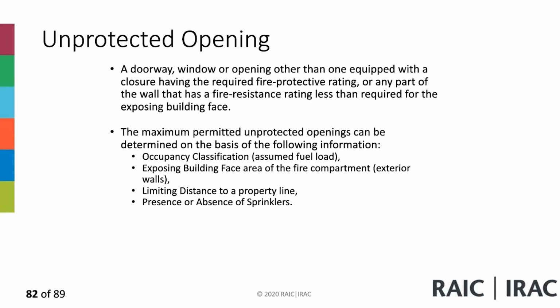So now the tables that relate to this are for determining, with the construction of the exterior wall, an amount of unprotected opening in the exterior wall. First of all, we need to determine what's the percentage of the building area that can be unprotected openings. If you are a designer and you would like to start off from this is the design I want, then you check how much unprotected opening you have against what the building code tells you can have.